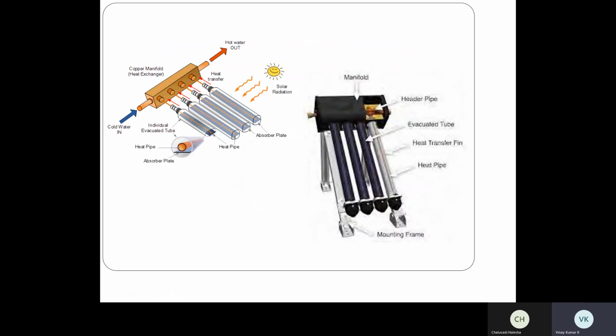However, the benefits are greatly reduced when conditions become unfavorable during cold, cloudy and windy days. Whenever atmospheric conditions get bad, that is, in cold, cloudy and windy seasons, evacuated tube collectors are best suited.